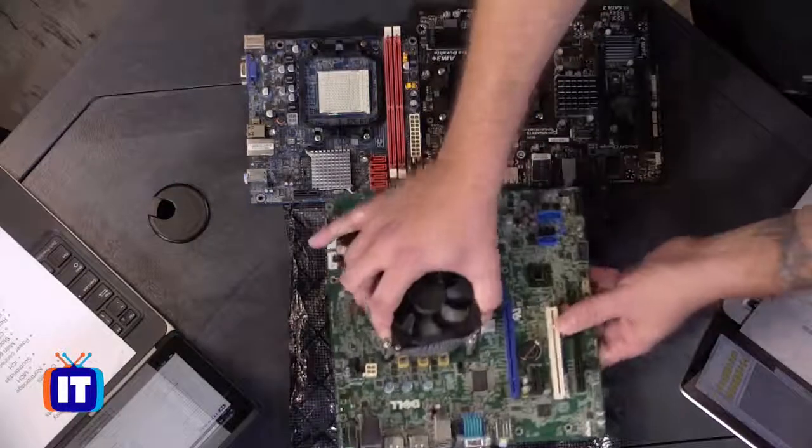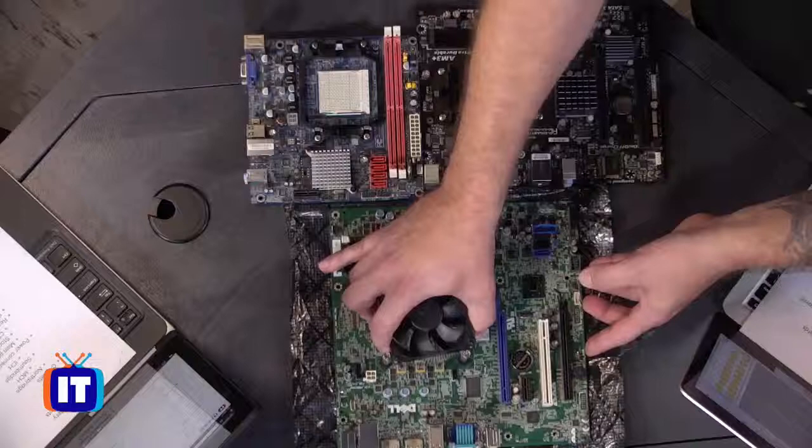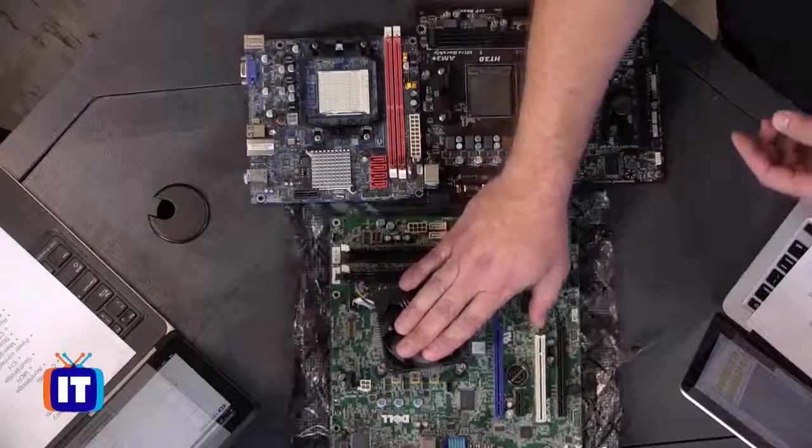Now, the other thing that the ATX standard did is it would rearrange, from the earlier AT days, it would rearrange the CPU and rotate the whole board 90 degrees to put that CPU, if you ever looked inside your case, the CPU is sitting right under the power supply. And that's because the fan of the power supply can help assist the overall cooling system within the machine itself.